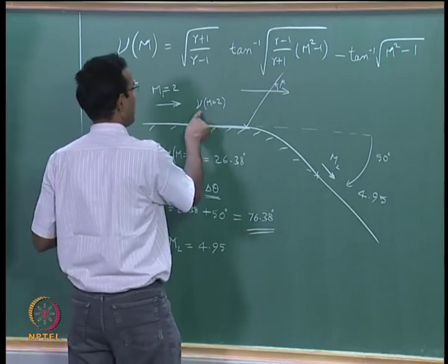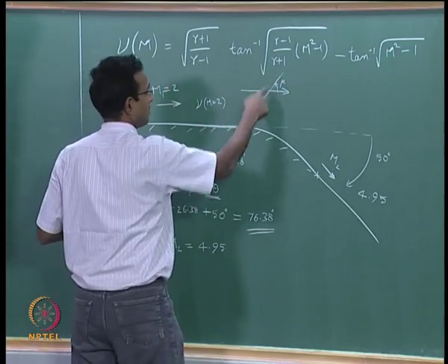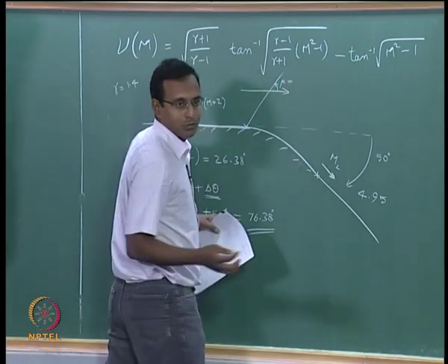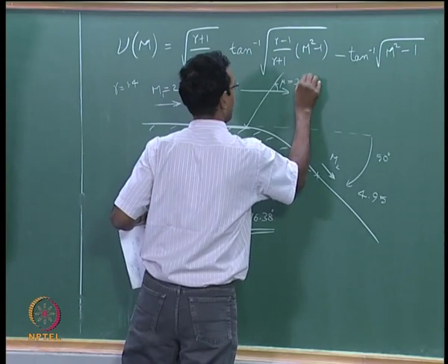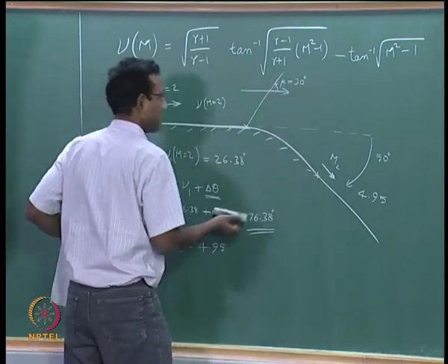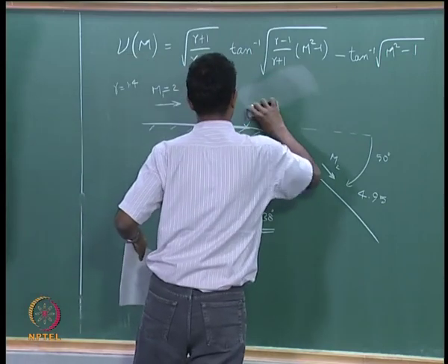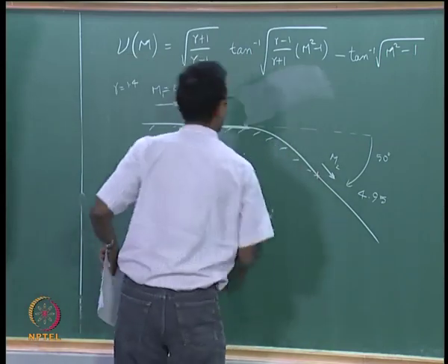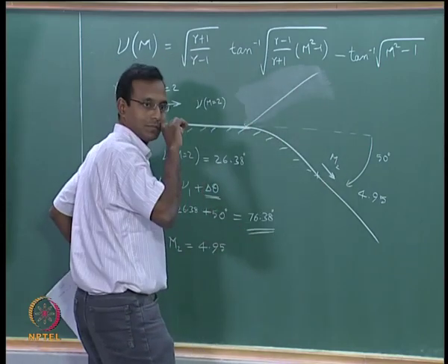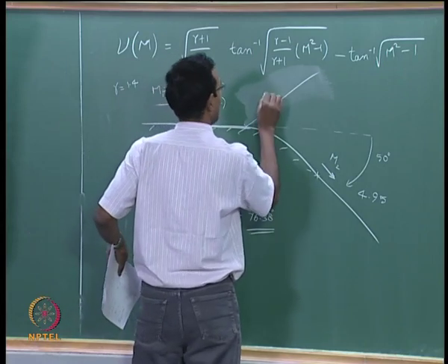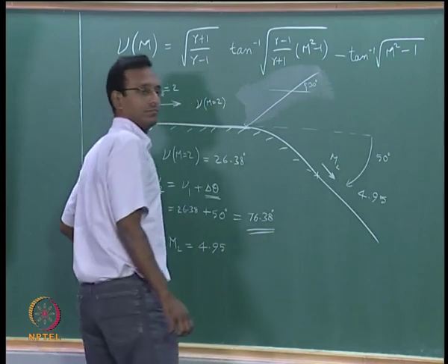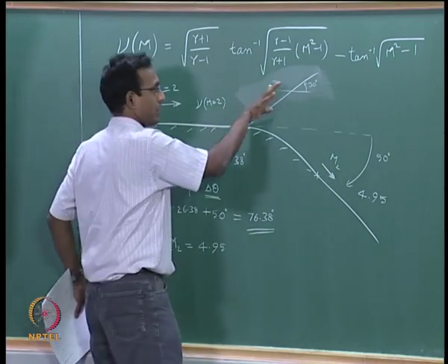So for M equal to 2, this whole region is uniform flow up to this first line. So for M equal to 2, the mu angle will be sin inverse 1 by 2, which is 30 degrees. So it should be drawn such that it is exactly 30 degrees. Since it is not very nice, I will draw it again. We will make it look like it is close to correct. So it is going to be more like this for this particular problem. It should actually be probably slightly lesser. But anyway, this is your 30 degrees. And it is going to keep on going there.